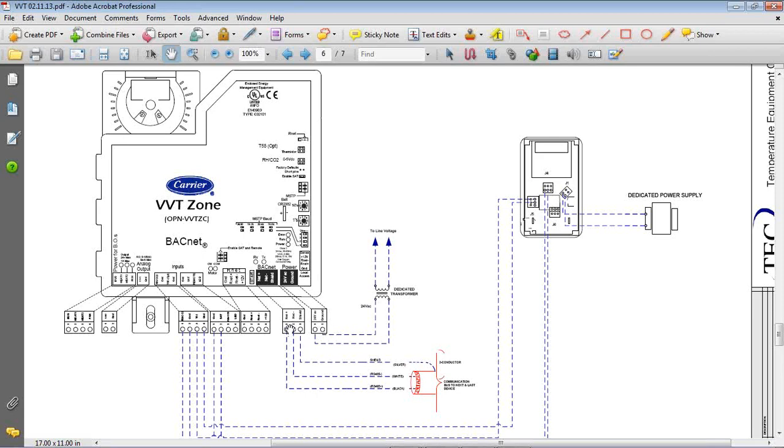Okay. So your 2-wire power connection is your first input here. Moving to the left of that, this is your actual communication input, which is a BACnet network. The BACnet network that we run on has to be 22 gauge shielded 2-conductor wire. Okay, so you can see you have your 2 conductors, your positive and your negative, going into 1 and 2 on that plug, and then you have your shield that actually lands on our terminal as well.